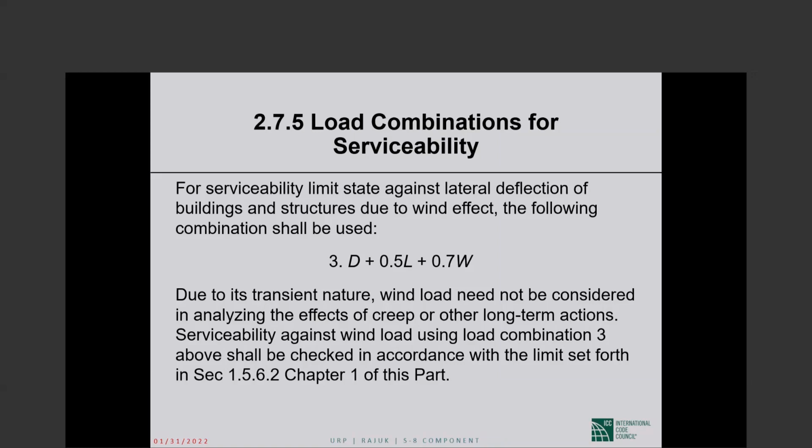In cases where, because you have a distinct lack of symmetry, dead and live loads may cause sideways deflection, you will take the short-term deflections. You will not worry about long-term deflections. This is what we are saying.